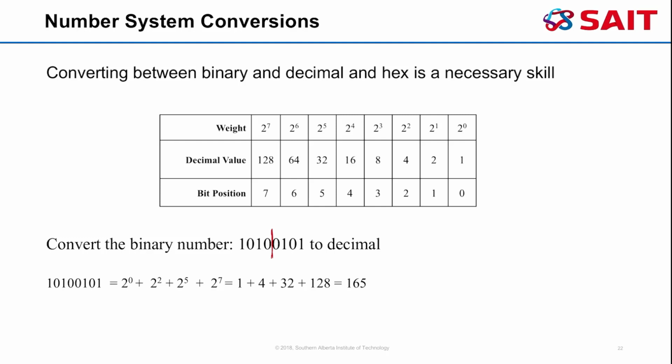So as an example, if I was to say the 1-0 information that I want you to know about is 10100101, it's easy for there to be a misunderstanding of what I said, or for me to make a mistake when I did that. Whereas if I represent those 4 bits as a hexadecimal value, which in this case would be hexadecimal number 5, and over here hexadecimal number A, I could simply say A5 is the value of 1s and 0s that I'm trying to communicate. And then once you took A5 and translated it to binary, it would be obvious the exact pattern of 1s and 0s I was trying to communicate.